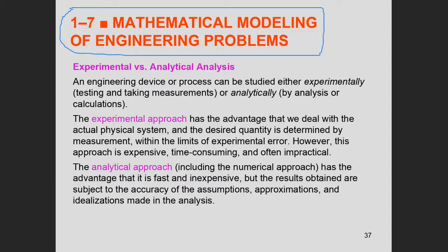Generally speaking, we have two approaches. We have an experimental approach, and we have what, guys? An analytical approach. Experimental approach is straightforward. You build a prototype. You have a car, you are designing a car, you want to understand the aerodynamics of the car. You build a small model of the car exactly identical to the car in reality. You put it in a wind tunnel and then you run the wind tunnel. The wind tunnel will tell you how the flow is distributed around the car.